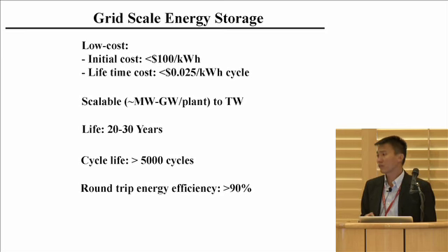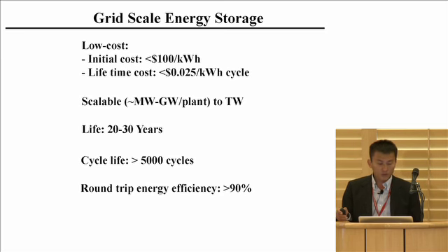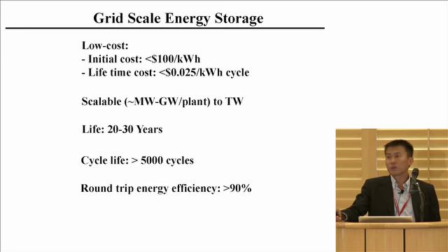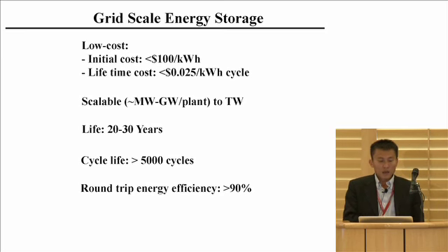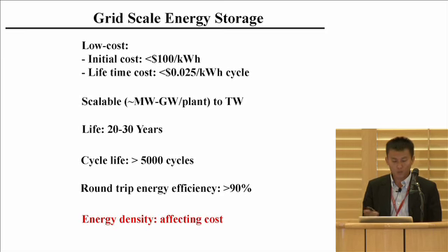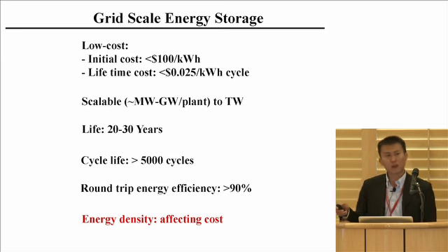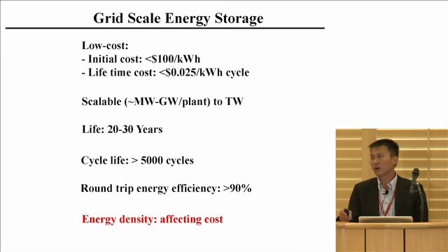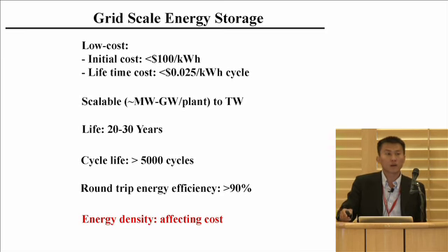You need high energy efficiency also. There's so much electricity pumping in and out of these storage devices. If your energy storage is not efficient, then you really waste a lot of power. So these requirements are different from what we are familiar with for portable electronics. For portable electronics, the first thing you probably think about is energy density: if I charge my cell phone, how long can I use it? But here, energy density is not the most important parameter, though it is still important in a sense, as it can affect the cost profile eventually.